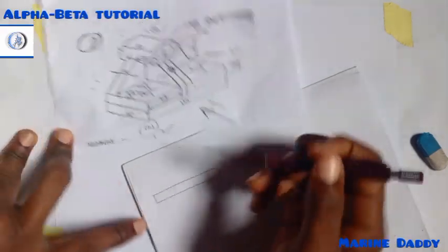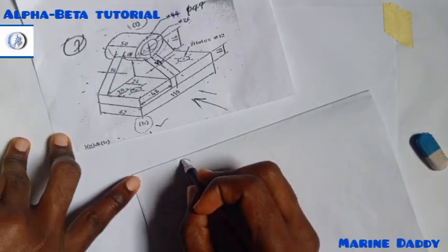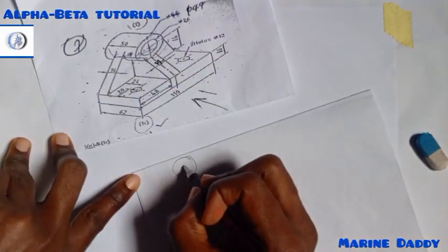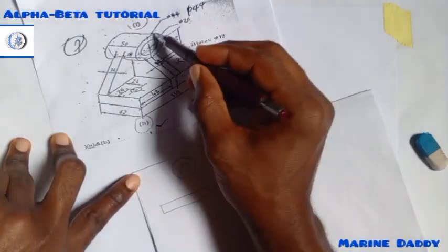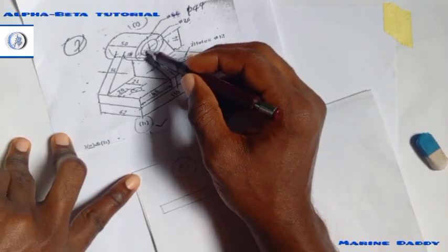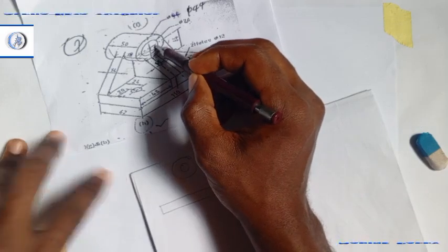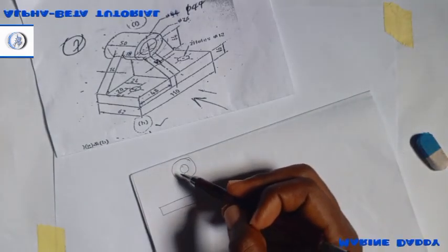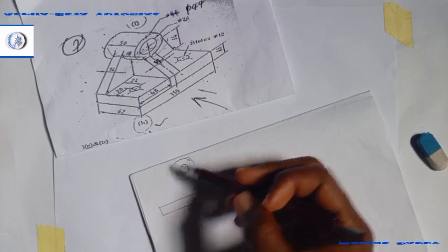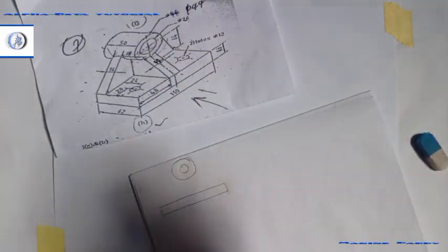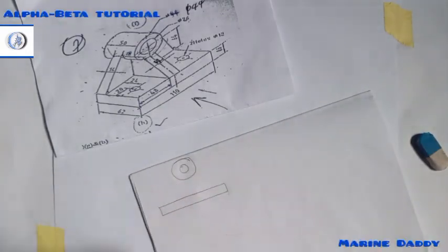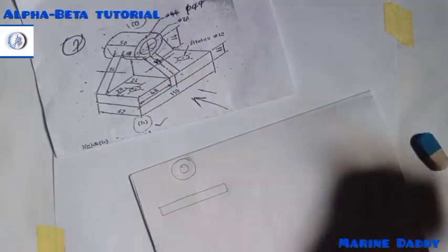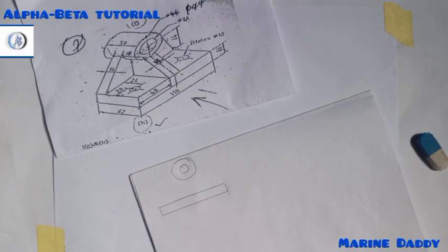Then this is my circle here. So let's say I drew my circle, this circle, and I also see this thing. Now mind you, this circle at this side is an isometric circle, isocircle they call it, because it's a circle drawn at an angle of 30 degrees to the horizontal. But in the orthographic projection, your isocircle becomes a normal circle which has equal radius from every part of the circumference to the center of the circle. So take note of that.